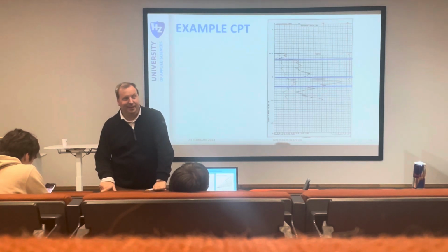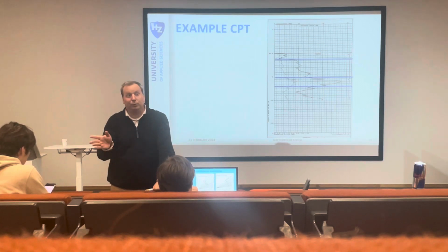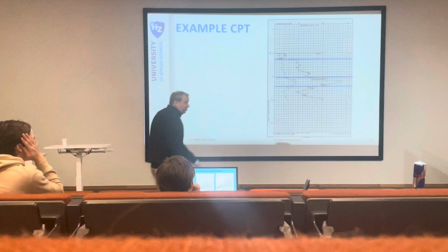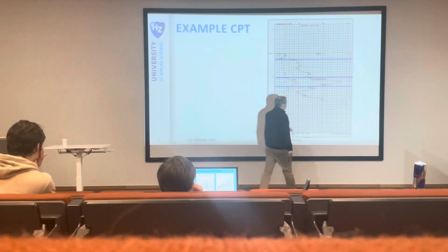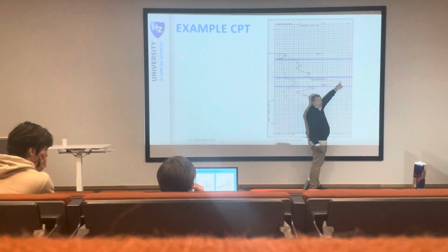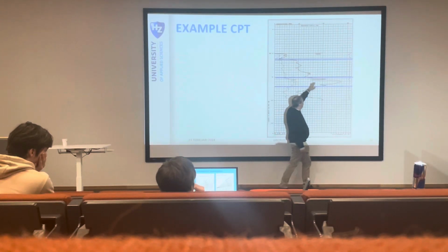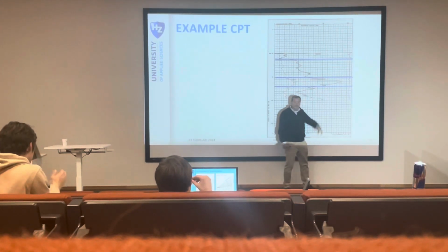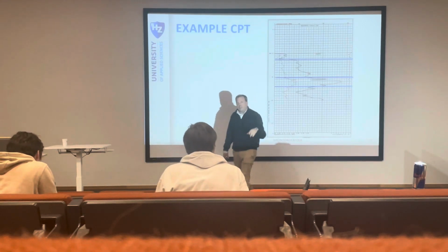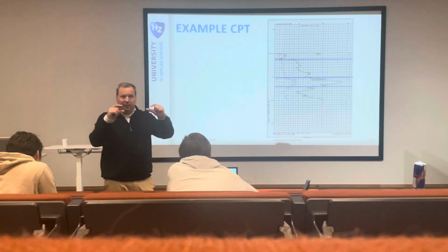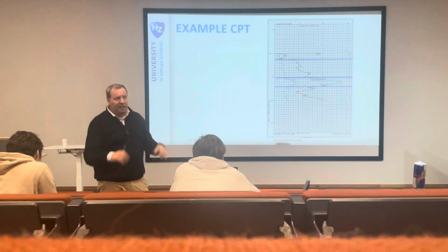Yeah. So sometimes when you see something very hard, you neglect it. That's why we always use averages. We don't say, let's calculate it at this point. We always make it in blocks, and then we take more or less an average. You don't have to do it for every millimeter to determine the type of soil. You take it in blocks.